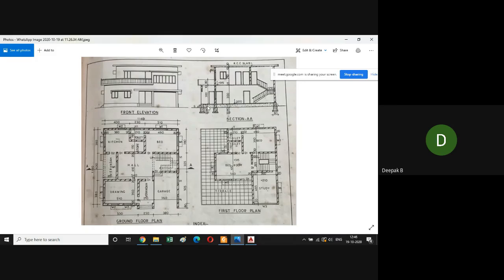So you draw the plinth, the projection of the plinth line to this place, and you will already get the 45 centimeter height. Similarly, the 300 centimeter height for the first floor slab here, and all the other dimensions also you will get directly from projecting.